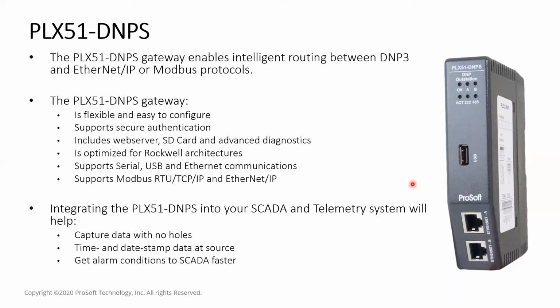And remember that DNP3 itself is an open protocol. So the idea is that we communicate to the controllers either using Ethernet IP or Modbus. We would then convert that data to DNP3 for communications back to the top end. It supports different types of connectivity, and it also supports both the Modbus and the Ethernet protocols for downstream communications.